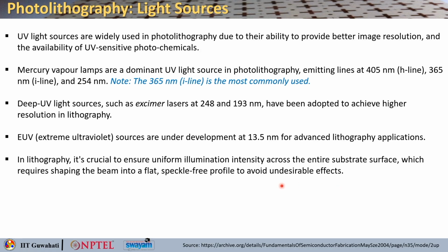When I say speckle free profile, that refers to the desired outcome of the lithographic process, where the pattern of the image produced on the photosensitive material, the photoresist, should be free from speckles or unwanted noise. These are the noise that comes from interference patterns. Speckles in the lithographic pattern can degrade the quality and precision of the final image, especially where you require very high resolution and fidelity, such as in semiconductor manufacturing.